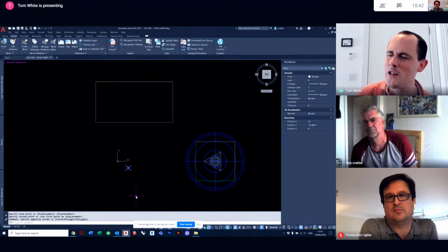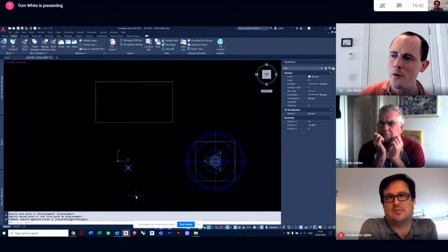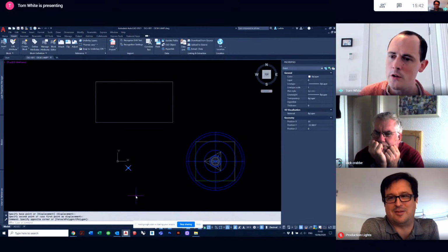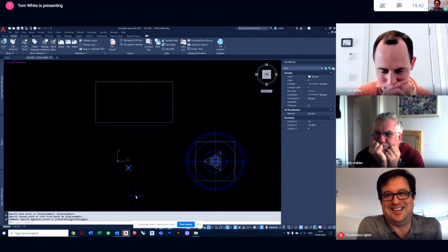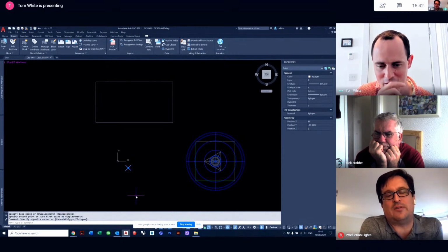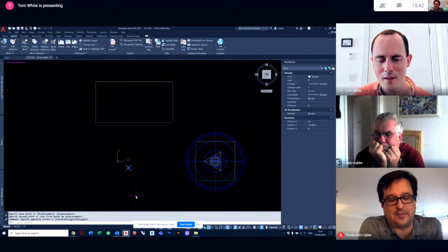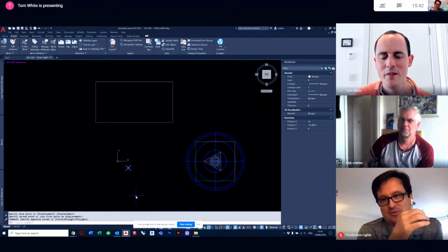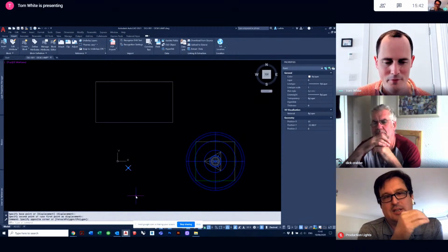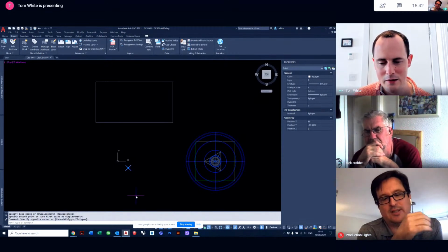Dom, do you know, is there a limit to the distance you can be away from the 0,0 of a drawing? There probably is. It's probably kilometers and kilometers. I'm afraid I don't know. All I can tell you is Vectorworks. In Vectorworks, the further you're away from the UCS, the more computing. It's always computing back to the UCS, or the origin, as it's called in Vectorworks. So the further away you get, the more it does.